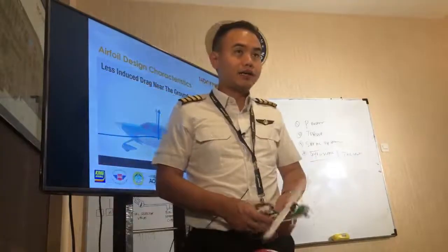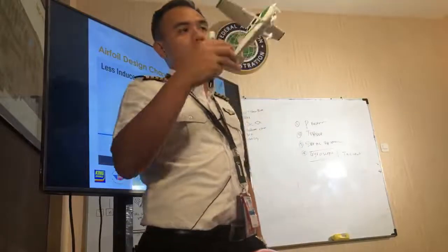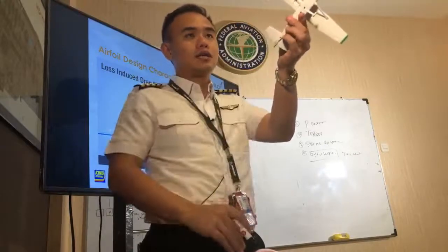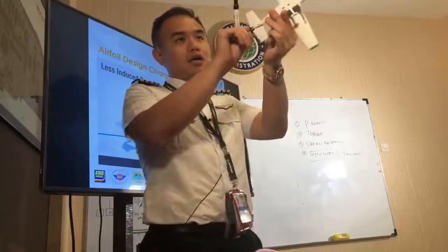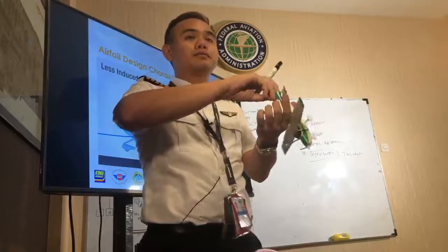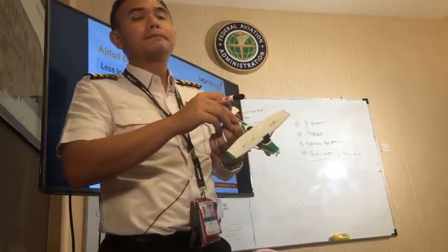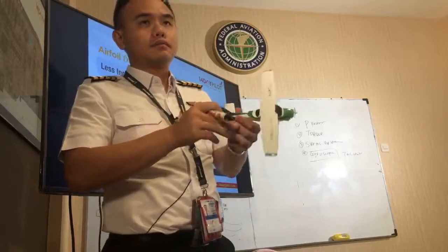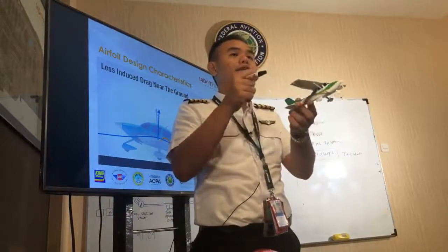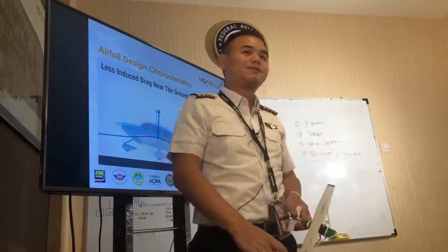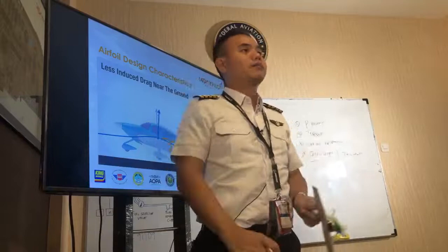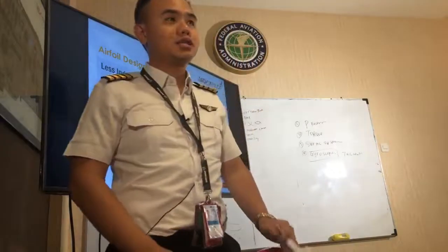Remember, so let's do it again. You're flying, you get distracted, your airplane stalls, your left wing gets stalled first, and starts turning. Since you're at a high angle of attack, you have yaw, you have roll, you have a spin. Power idle. Ailerons neutral. Rudder opposite. Elevator down, break the stall, and recover. This is a fail item. You cannot forget it. You have to always remember, because once that happens to you, this will save your life.